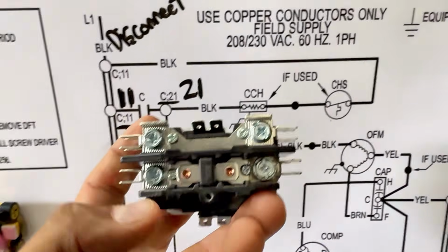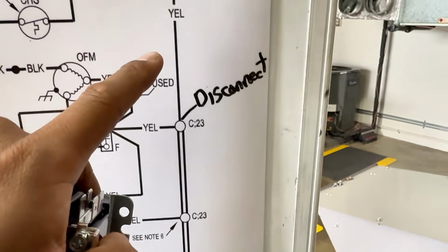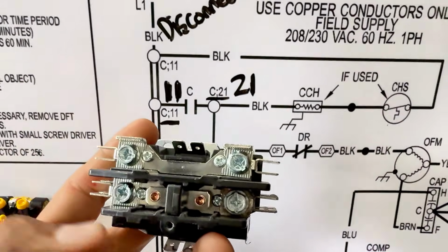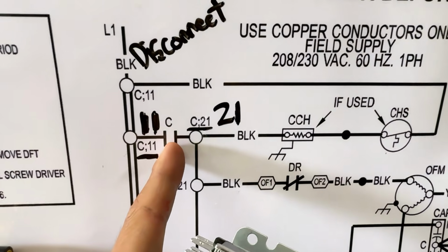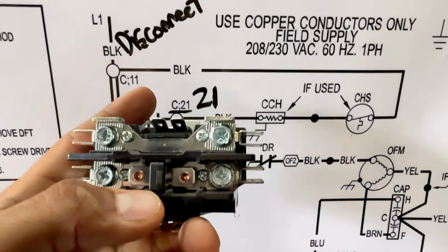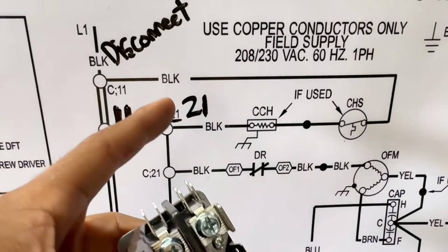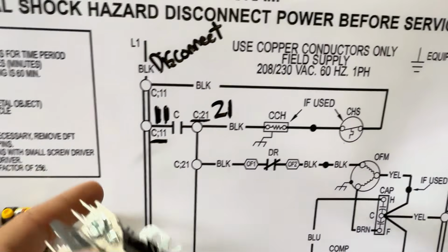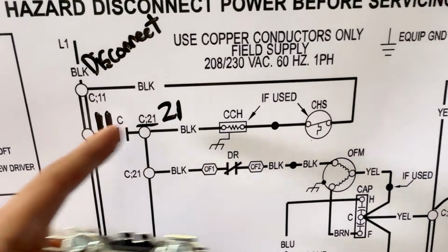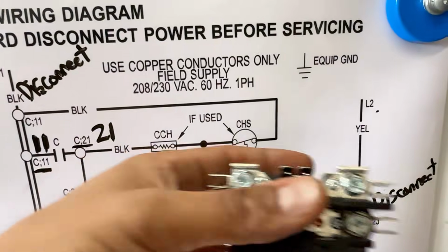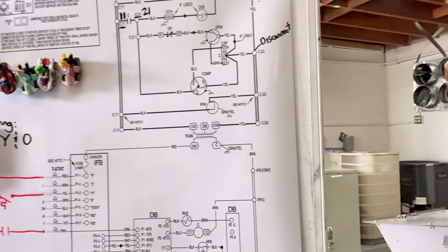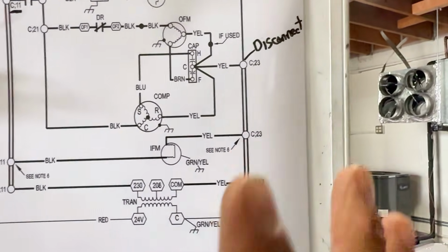So if you were to look at the contactor again on top, 23, you see, there's nothing stopping it. It's just full flow. Power's just going to go through. But 11 and 21, that's it right there. This is an open contact. So as I had mentioned, if I want to close it, then yes, we can go ahead and draw a line close, which we'll go over right now, but I need to send 24 volts right here on the coil so that power can go through. But do you see the contactor, all the wiring, it's already there for you. You don't have to worry so much about the high voltage wiring. It's already there.